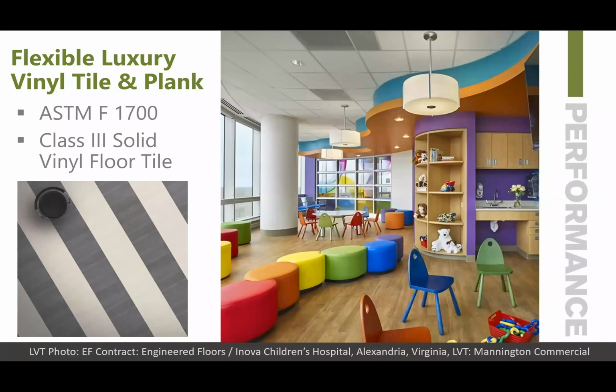So there are 3 classes within the ASTM F1700 standard, and vinyl tile and plank, LVT and LVP, are in class 3 solid vinyl floor tile when you're looking at performance information. Understanding the application of the product and the performance needs, not only in healthcare environments as shown in this photo, but throughout all types of settings, is critical.